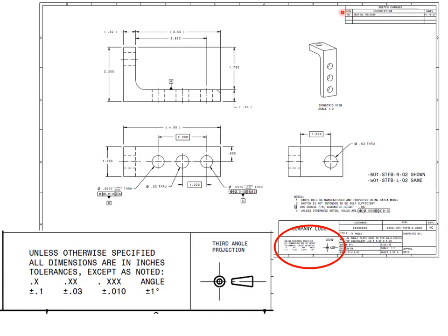Once we make a change, we would now use the alphabet and start with the letter A and a brief description of what you changed. Diameter 0.59 changed to 0.65 diameter. Look at zone 6B. So this is letter B, this is number 6. So you tell them at zone B6, look in that area, look for that dimension.